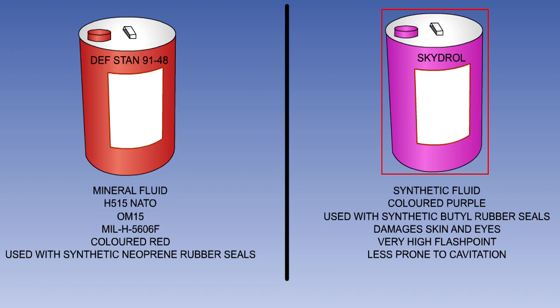Skydrol is the most dangerous to personnel, but most modern airliners use Skydrol in their hydraulic systems. Both of these fluids are flammable if subject to sufficiently high temperatures and a source of ignition. However, because of its very high flash point, Skydrol is much less so.